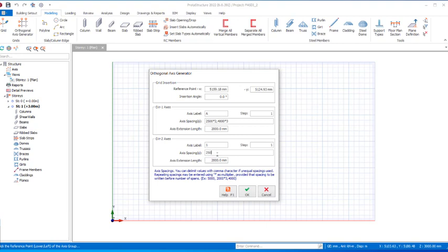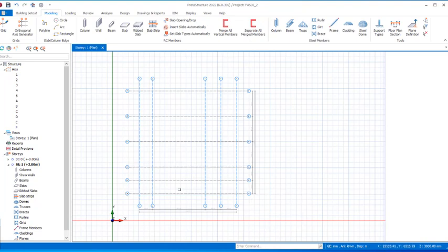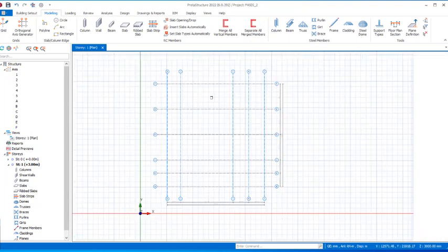We also have 2500 right there, and then we have a comma, and then the main auditorium is going to be 10,000 millimeters. All right, and then you have a comma, you have also 3000 as part of the auditorium, and then we asterisk that with 2 places. All right, so the total width is going to be about 16 meter. After which we click on the OK options. So we have our grid line set out just like this.